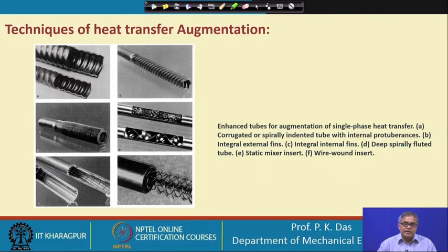D, there is again on the tube geometry some variation. So, that will give some enhancement in heat transfer. Below what we can see, here we have got some sort of a tape insert in this diagram. We have got a tape insert inside the tube. So, the heat transfer will increase. Here the last one, we have got some sort of wire insert inside the tube, which will give good mixing and better heat transfer.